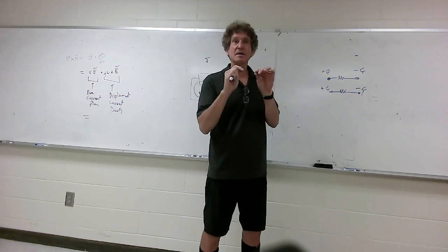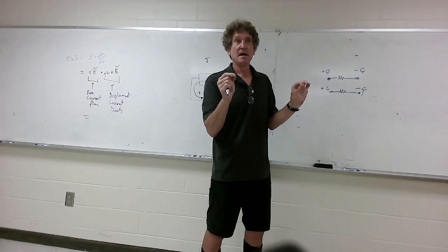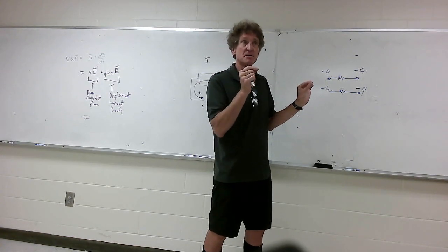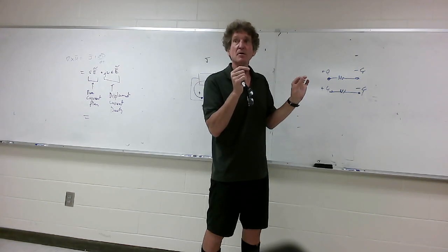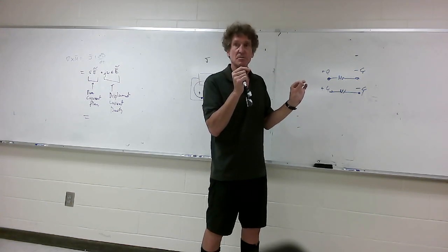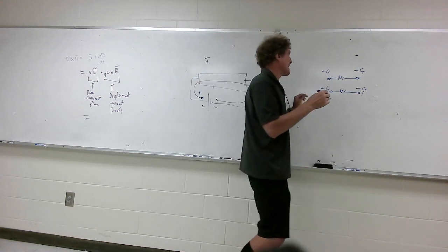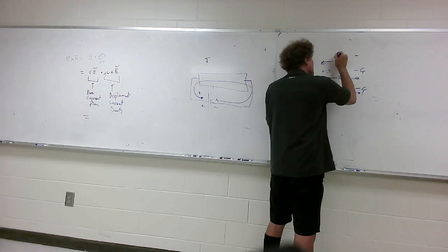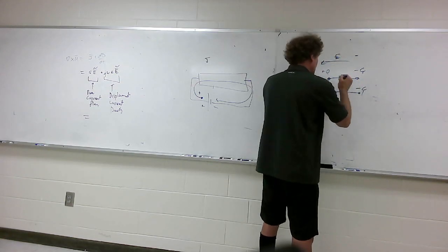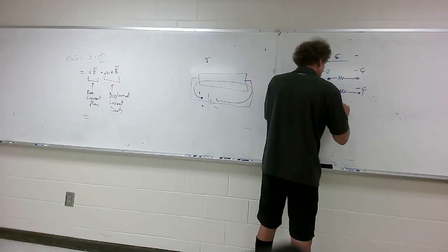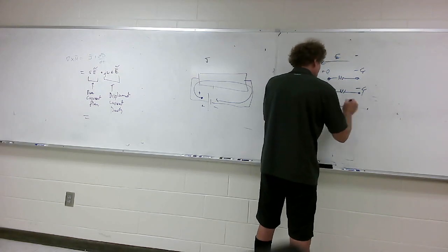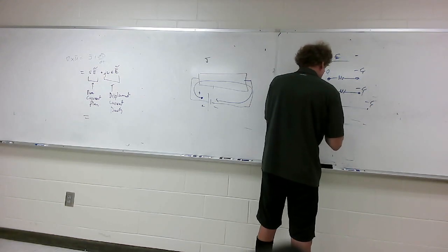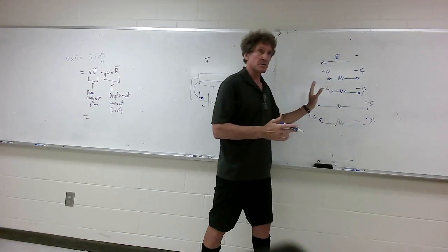What it represents is what's going on inside a dielectric like mica or any kind of dielectric material. Dielectric materials typically are considered insulators, so they don't allow DC current to flow, at least not much, almost none. Follow? Now, if you apply an electric field in this direction, then these molecules stretch. This molecule and this molecule will stretch, and as they stretch, there's movement of charge. Y'all follow me?